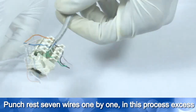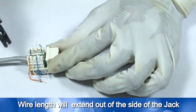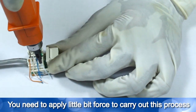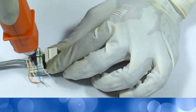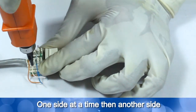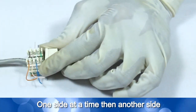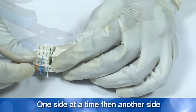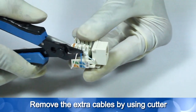In this process, excess wire length will extend out of the side of the jack. You need to apply a little bit of force to carry out this process. It is also recommended to punch down one side at a time, then the other side. Remove the extra cables by using a cutter.